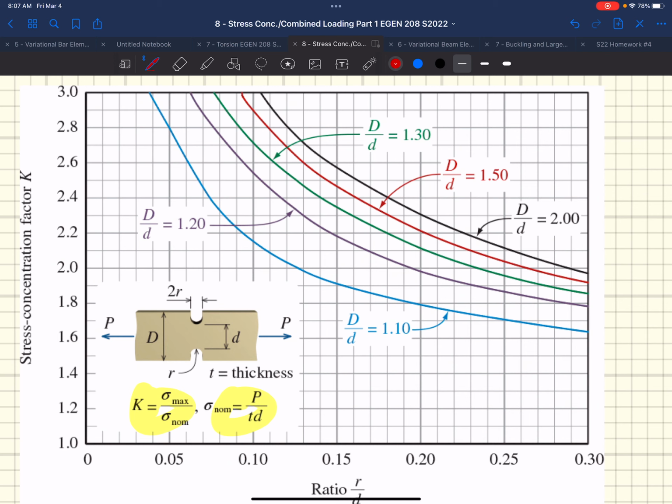What you have to be careful of is when you calculate that nominal stress, depending on the solutions, depending on the text that you use, is based on certain dimensions of this notch. And in our text, it uses the small dimensions of our cross-section. So our nominal stress that you'll calculate, right, we'll know either a notch radius and an overall dimension, or they might even give us just the dimension of the notch, right, what's left of the material.